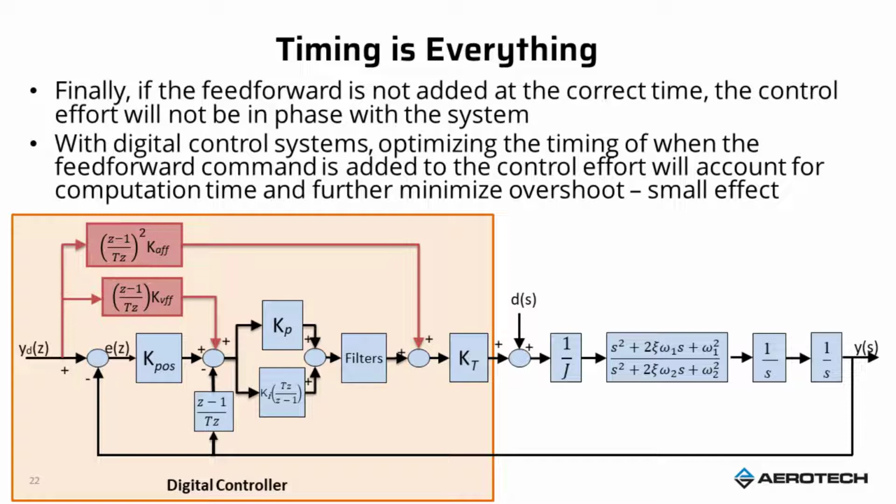And then if I look at, say, a position or servo loop that is operating at a kilohertz and a current loop that's operating at, say, 20 kilohertz, then I'd have quite a few samples to select when that feed forward gets injected into the current node of the system.